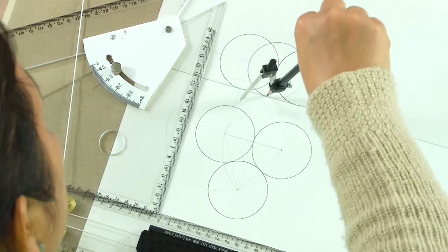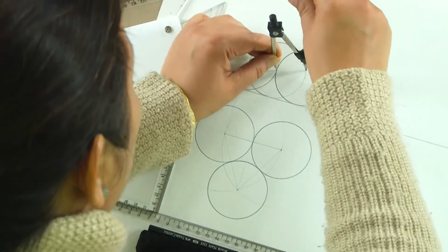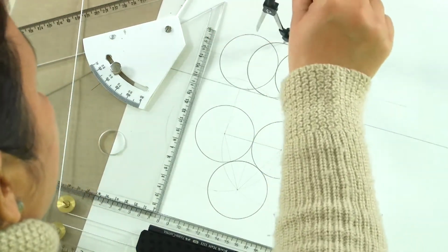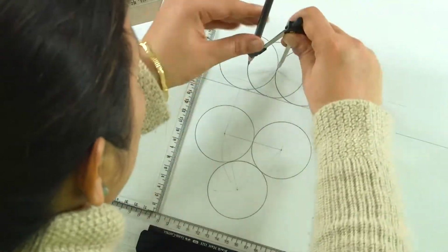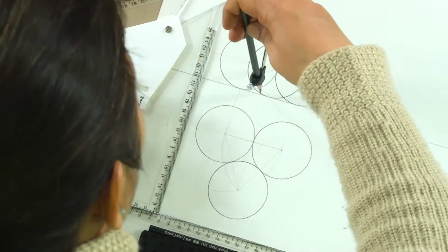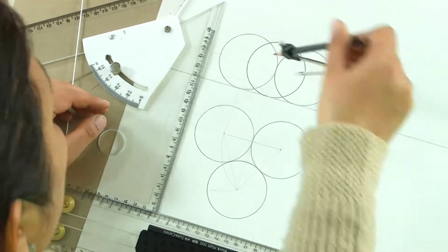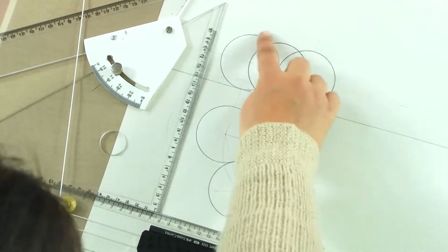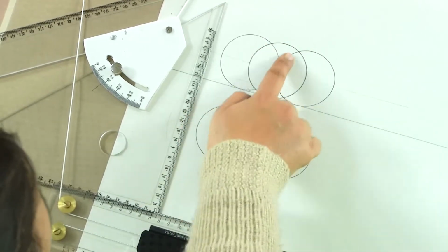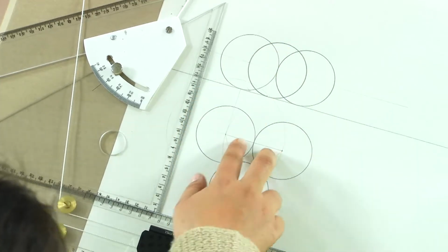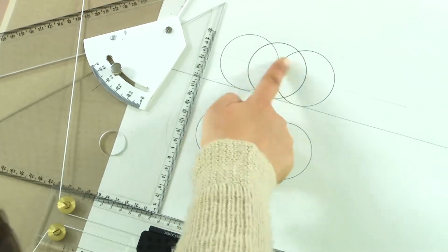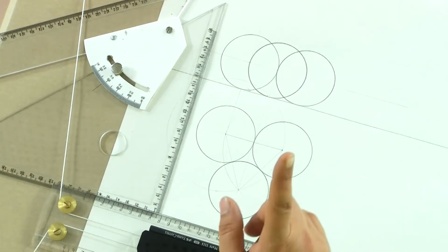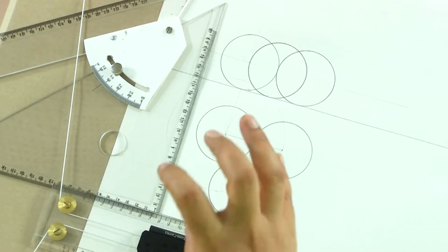Since I am drawing on the existing drawing, I am not making a new drawing, that is why our hidden lines are actually currently depicted as solid lines. However, if you knew already that there are three spheres and that is how they are going to be placed, we would know that anything which is behind this front circle is going to be hidden. So these two curves representing this portion behind this are actually going to be hidden. So it could be any arrangement of spheres which are of the same size.